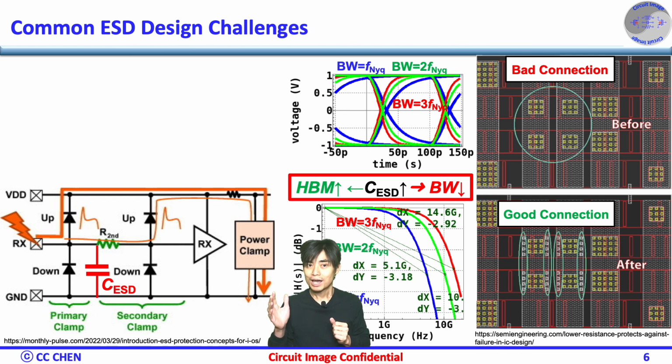Circuit simulation helps predict how ESD structures impact performance. Placement is another challenge. Poor routing may make protection ineffective. ESD current must flow along the intended path to avoid unintended damage. Advanced packaging techniques also influence ESD robustness. Some designs require custom ESD solutions tailored to specific applications.